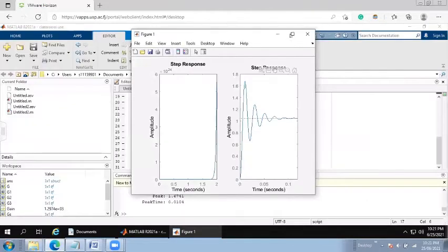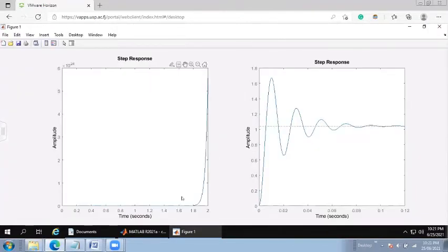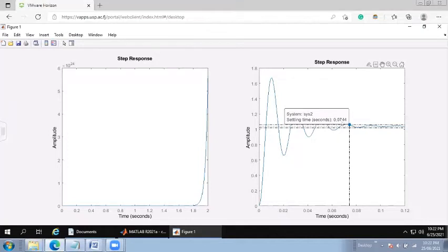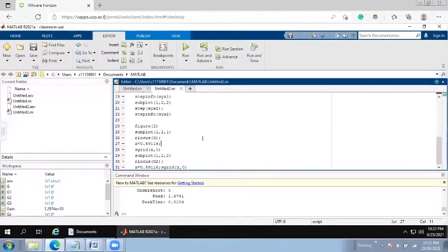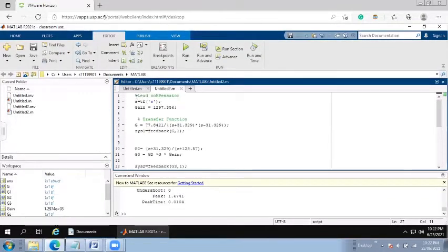And for figure 1, which was supposed to show the step function, this was the original step function without the compensator towards your left. We had to get a settling time of less than 1 second. I can successfully say that we were able to receive a settling time less than 1 second for the value 1. So this proves that the coding done for the lead compensator was actually correct. I'll just take you through the other section, which is for PD control.